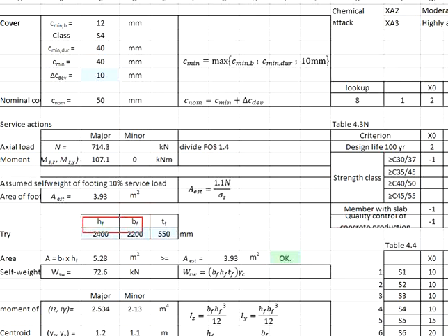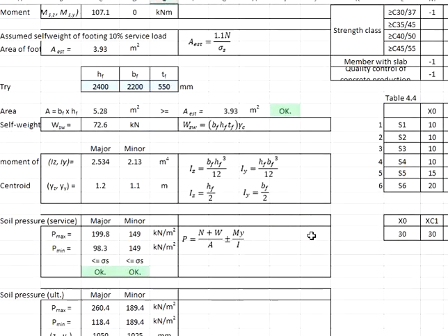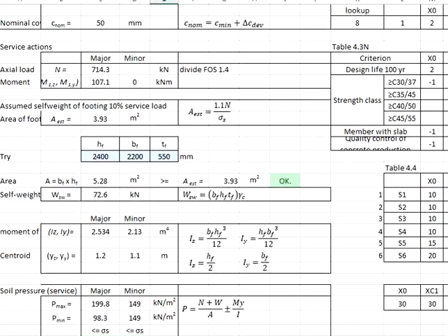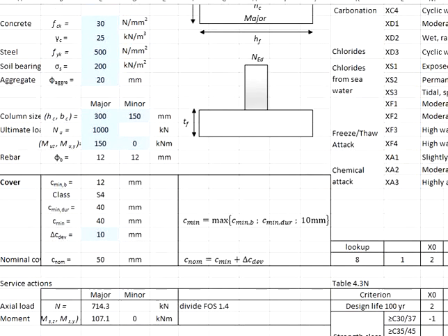You can do trial and error for any shapes, as long as the contact surface area is greater than what is estimated. However, later you will still need to check to confirm that the proposed size passes the design. The contact surface area is not the ultimate criterion for us to determine whether the proposed size is adequate. The reason is that when you estimate the area, this is on the basis that the pad footing is subjected to pure axial load, where there is no moment. However, in this case, you have moment.